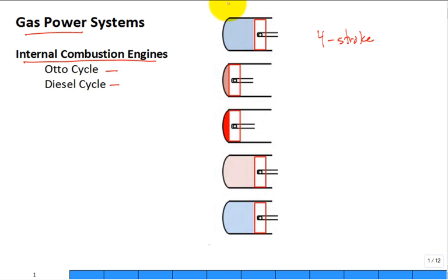What we're showing here is the piston at bottom dead moving to top dead. As you compress it, it changes color. It's showing it's warmer. Then here for the Otto at top dead center, there's combustion. Now it's really hot, high pressure. You undergo a power stroke, and then you undergo heat transfer to reject. So heat addition at constant volume, and then heat rejection at constant volume.